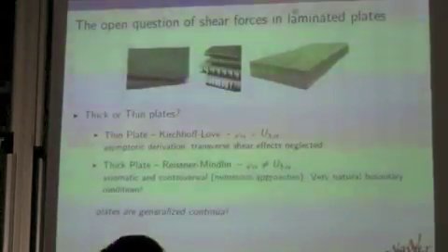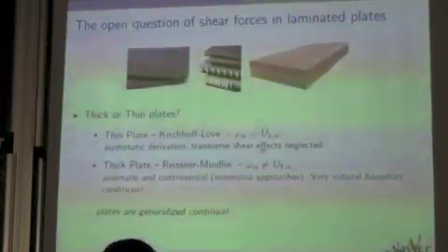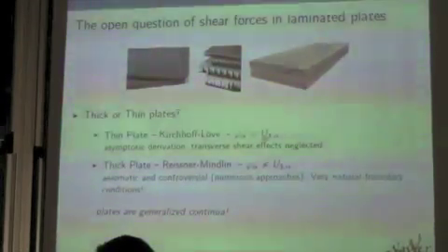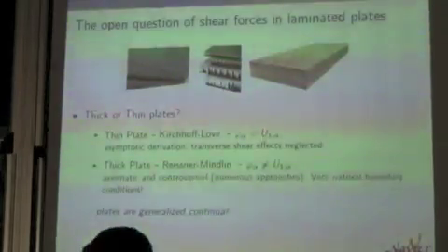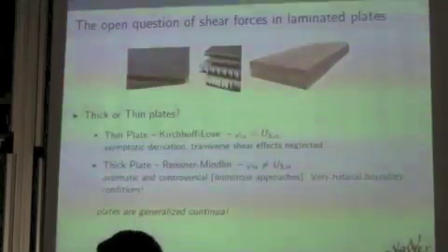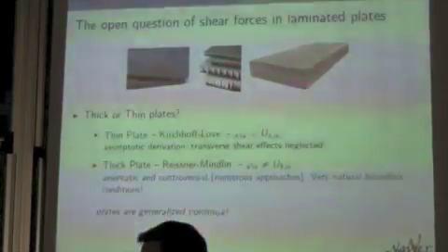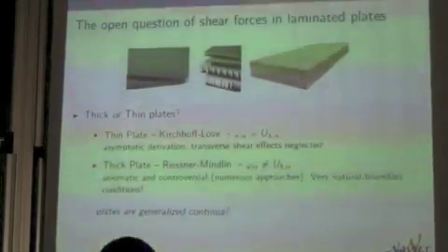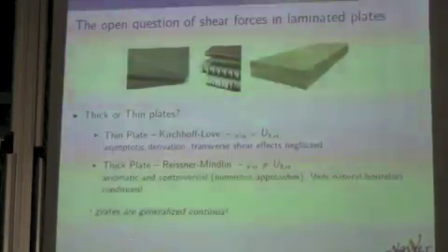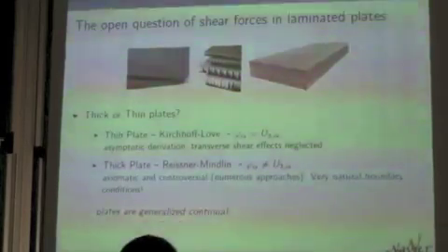The thin plate model is a Kirchhoff-Love plate model, and the common assumption is that the rotation is equal to the slope of the midplane of the plate. This model is very ancient and very well known, and it was also derived from asymptotic expansions. So it's the leading order plate model. The matter is that with this model, you don't have the transverse shear deflection, and you neglect the transverse shear effects in the approximation.